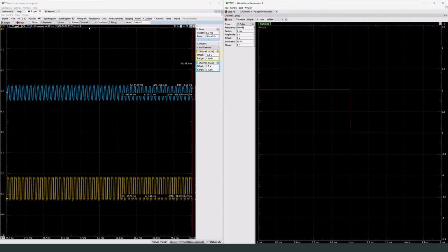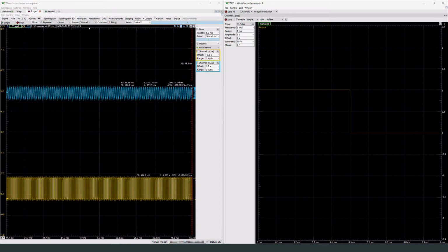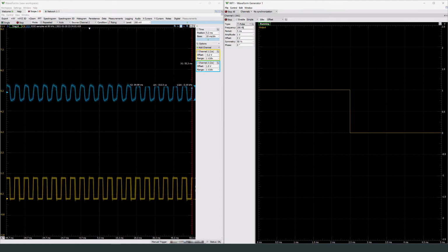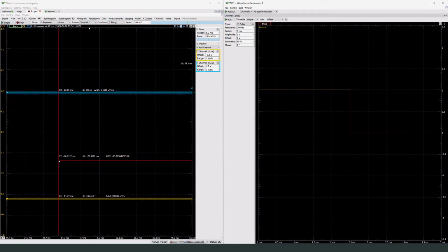But if we go above 500 hertz, which will start to really decay pretty quickly for our low pass filter, you'll see that the output starts to shrink. So if you try to get too high of a frequency through there, the volume's just going to go down, right? So this thing was designed to operate between the two frequencies that we cared to use for our project. And so that's what it looks like if you just send in a square wave. And so now I actually have the code in the Arduino hooked up here.